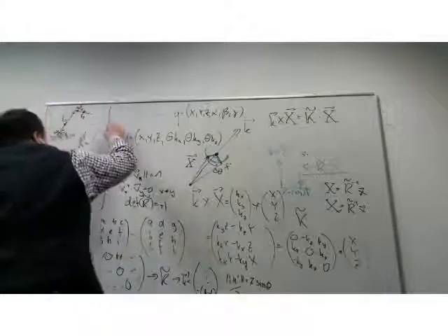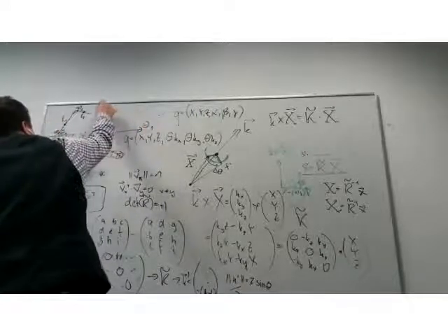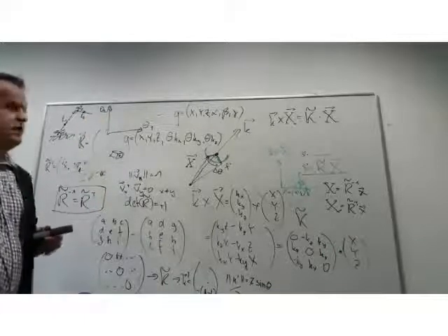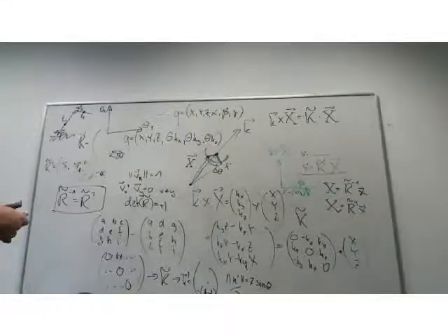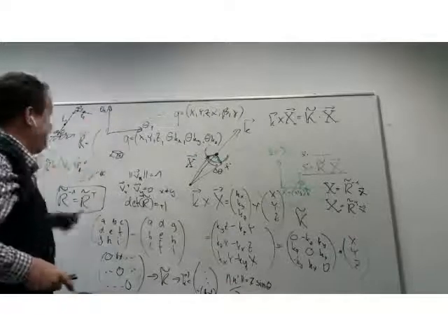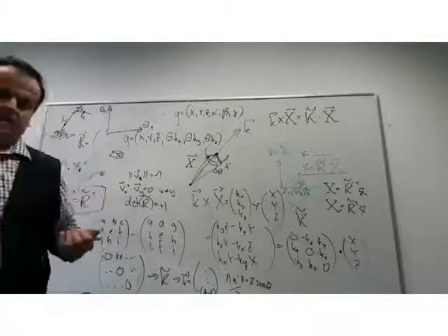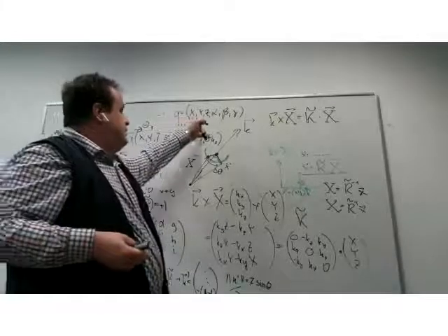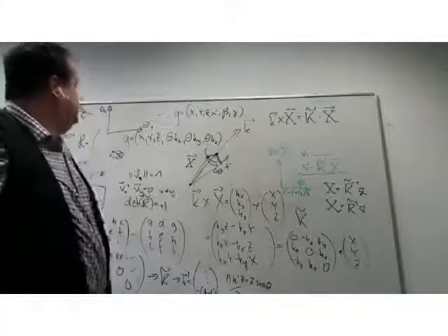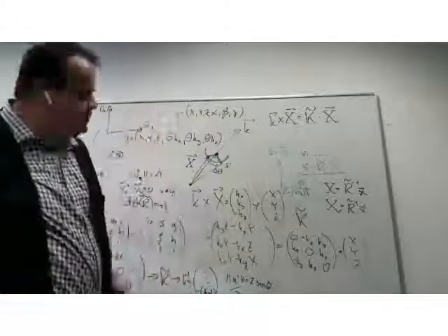That's why our configuration space for this rigid robot with 2 rotational links is completely captured by the current orientation of theta 1, theta 2. So the configuration of a free-floating object is defined by the 6 parameters of free motion.